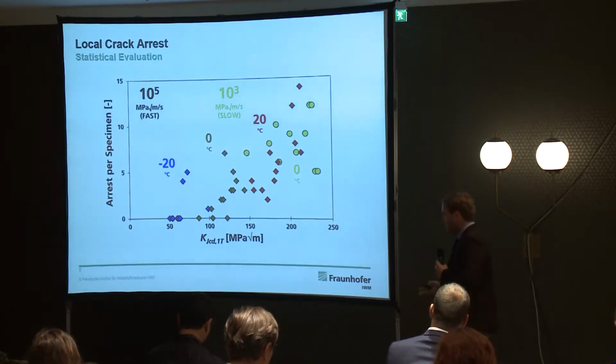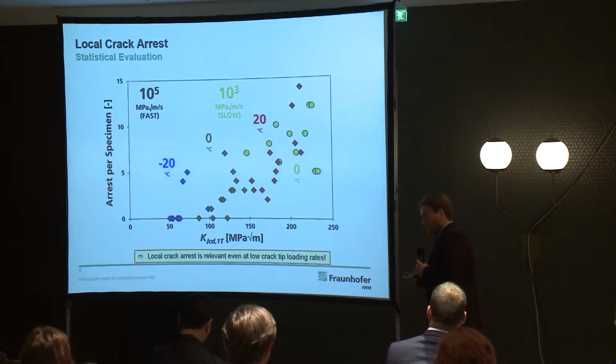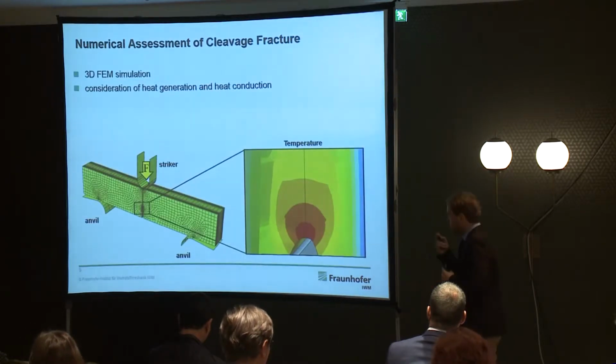We see here that at lower crack tip loading rates, we even have the same relevance of local crack arrests here. So that's a very interesting conclusion, that the fracture behavior is fundamentally changed as soon as we elevate the loading level just a little bit.